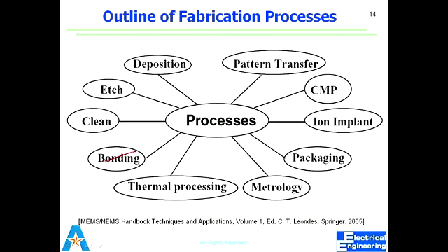Why do we want to do it in the substrate itself? Why not use an external resistance? Can I use an external resistor? Size? Size. How are you going to bond a million resistors? That's the basic idea of an integrated circuit. Everything has to be integrated. Everything has to be within the bulk, next to each other.